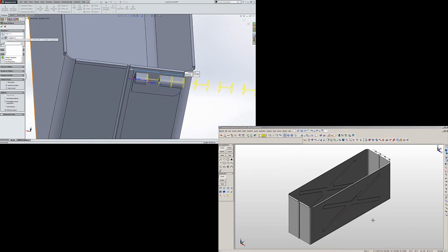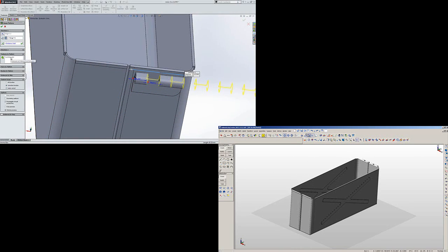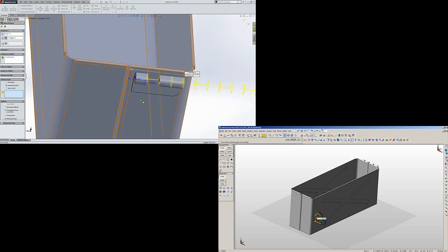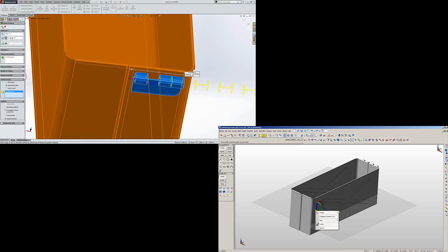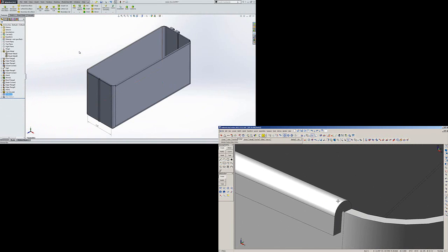And our instances, that's going to be another global variable that we created, and it's going to be our odd. Alright. Now for features to pattern, it's going to be that cut automatically selected, and we're just going to have it on just this body here. Okay there. So that cuts away quite nicely like so.